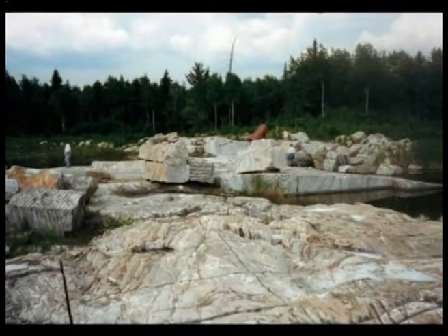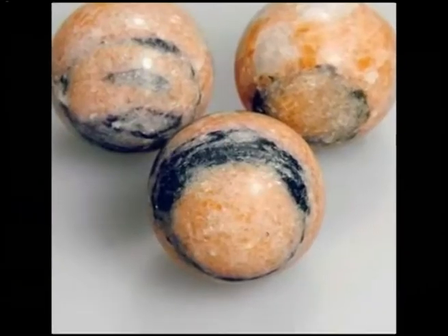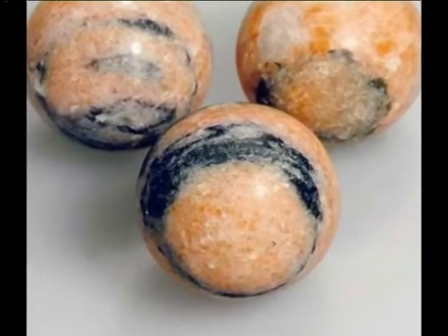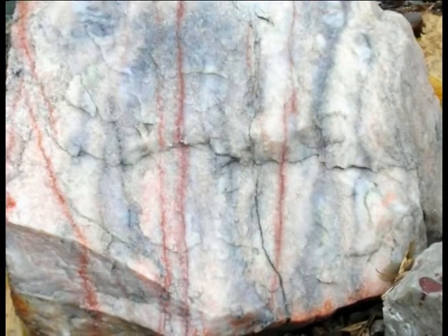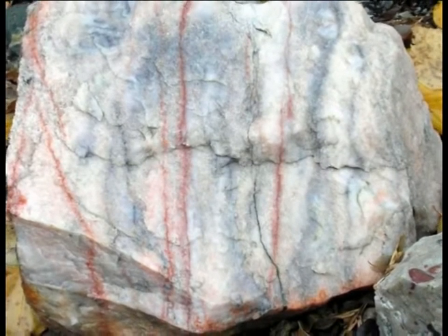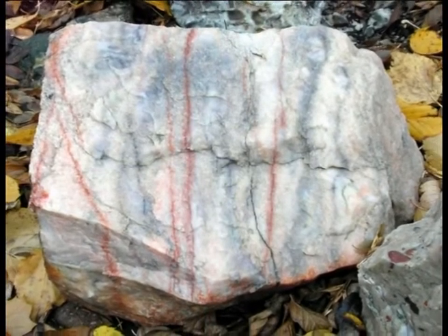Marbles. These are metamorphic rocks that are used for ordinary structural work as well as for decorative purposes. Marbles vary in texture, color and composition. Their absorption value is generally below 1% and normally they possess sufficient crushing strength. They have been extensively used as decoration stones because of their susceptibility to brilliant polish and beautiful colors.